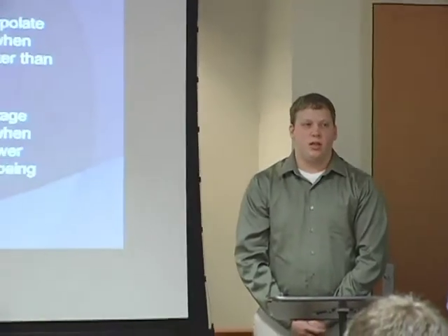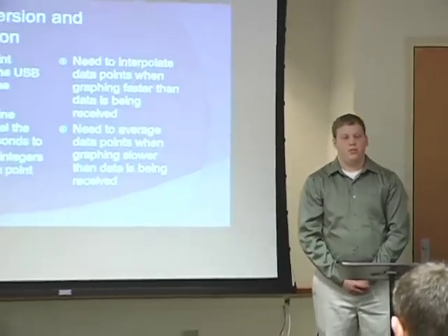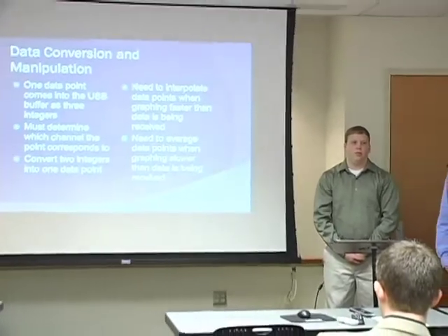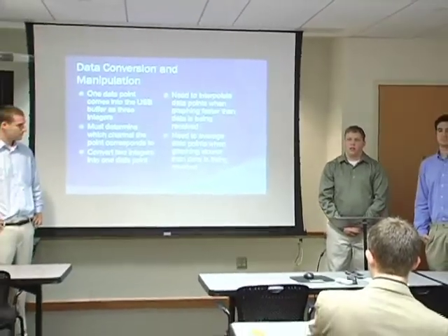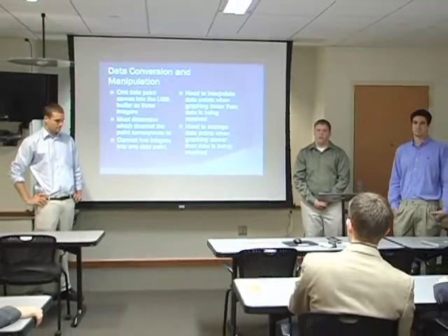And my goal, or my task, was to first determine which channel the point was coming in on by using the command byte. And that would also tell us the speed that the data was being plotted at. And then after that, I had to get the most significant bit and least significant bit, and I would have to shift the most significant bit and add them together to get our one data point.